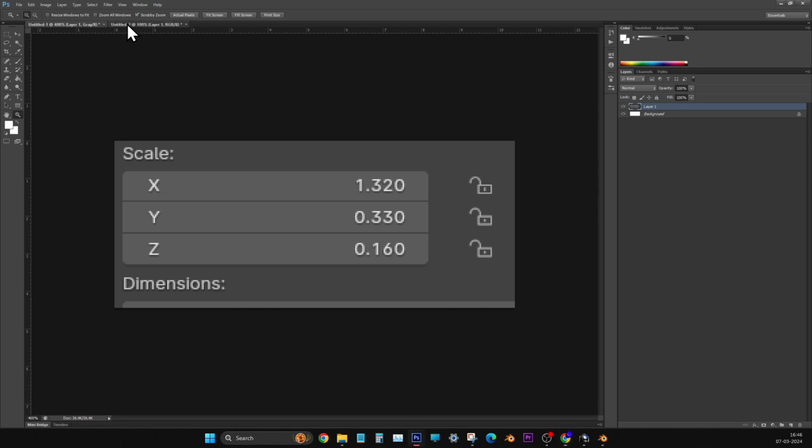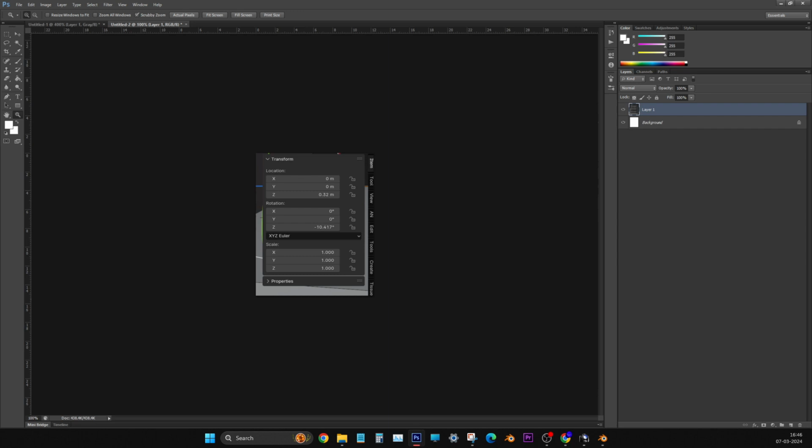Now you have to just move it a little. Go to the move option in the toolbox. This x-axis handle is there, no? Move it to the left side using that handle. Press and hold Control and then move it. It will snap. Press and move it with the left mouse button.